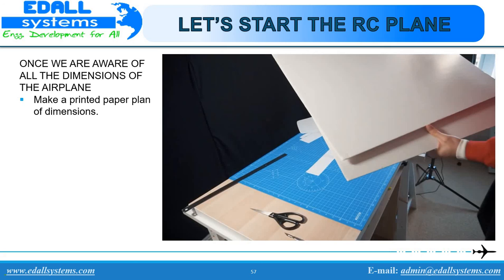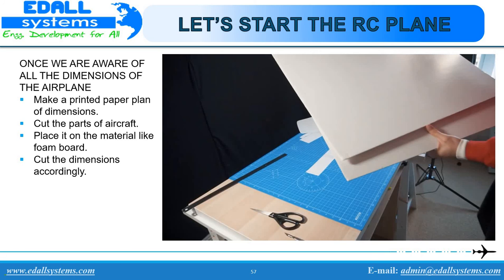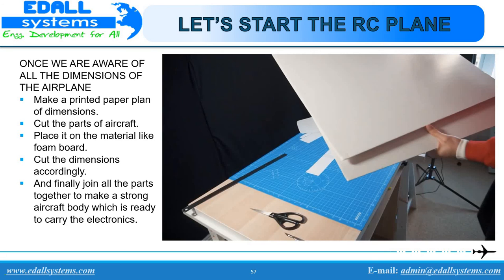Make a printed paper plan of all the dimensions. Cut the parts of the aircraft. Place them on the material, like a foam board. Cut the dimensions accordingly. And finally join all parts together to make a strong aircraft body which is ready to carry electronics. Now we are done with the calculation and construction part of the RC model. Let us move on to the electronic construction of the RC model in the next session.